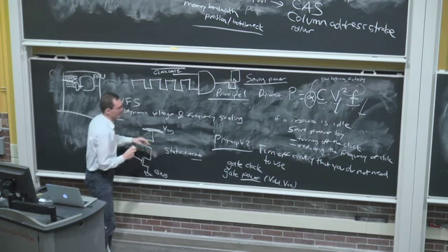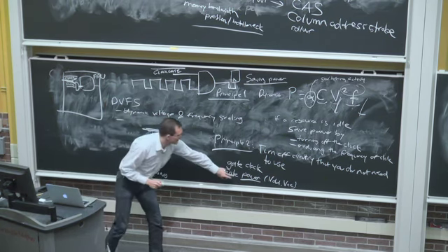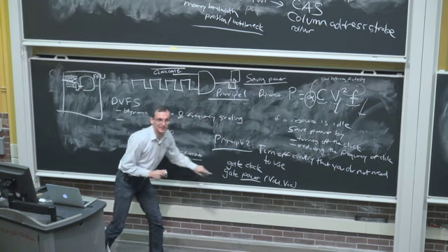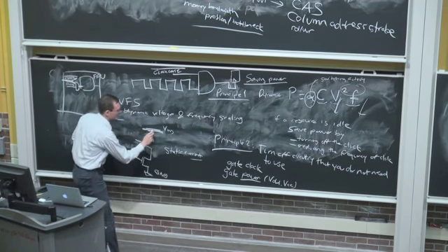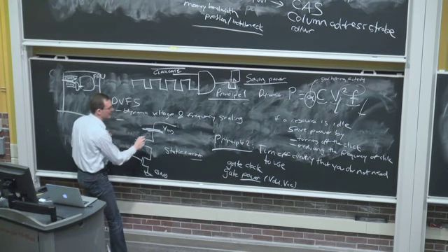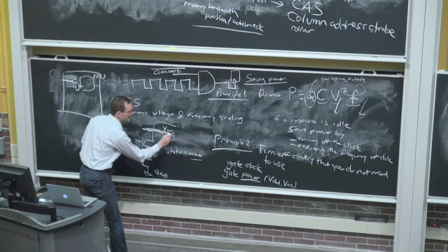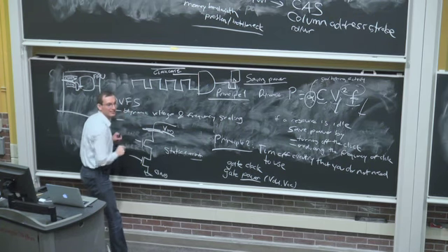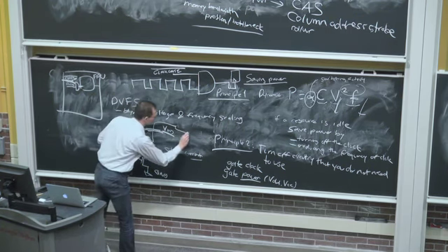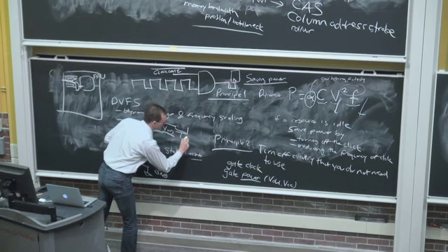So how do you actually save this? And that's the idea of gating the power. You could have transistors, and there are different ways of doing this, that gate this VDD such that the VDD is not supplied to the circuit. And this is sometimes called a sleep transistor, if you will.